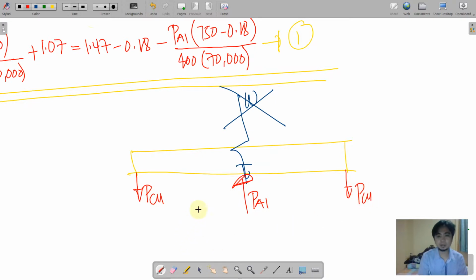Okay, so we have actually established that aluminum tends to push this upwards, and as the copper is fixed and attached to the slab, as this slab goes up, of course there will be a resistance on the copper, and that is a tensile reaction.